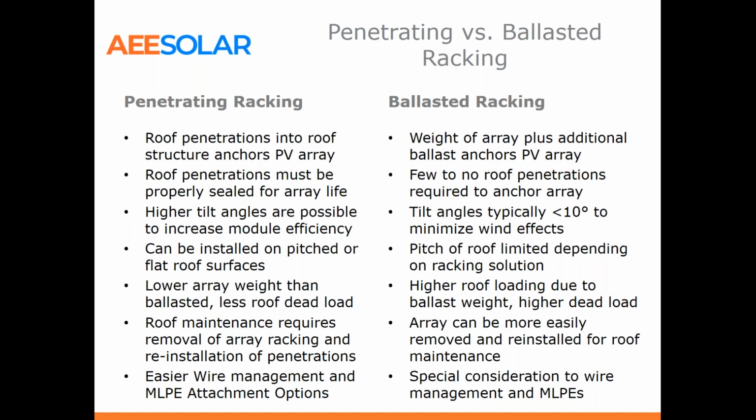So for a ballasted racking system, of course, we want to try to use ballast blocks or as few penetrations as possible there. But we can also design to any PSF dead load that you want. And typically, if you do have a ballasted system that is anchored by penetrations rather than by ballast, you'll have a lot less penetrations than if you were going to a full penetrating array.